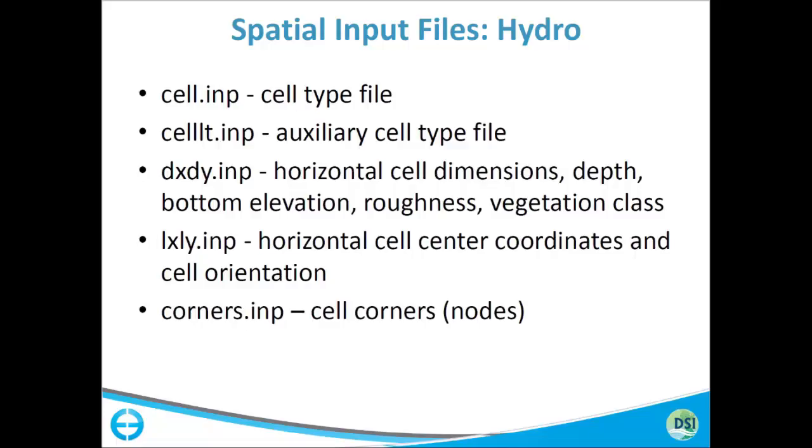what's going on, especially when a model has poor orthogonality. You guys talked about that yesterday, I guess, with the intro. Model orthogonality is important for EFDC. We like to try to keep the deviation from purely orthogonal, which has a value of 0 degrees, to something under 3 degrees. That's fairly common, and usually a good target to have your model less than that.